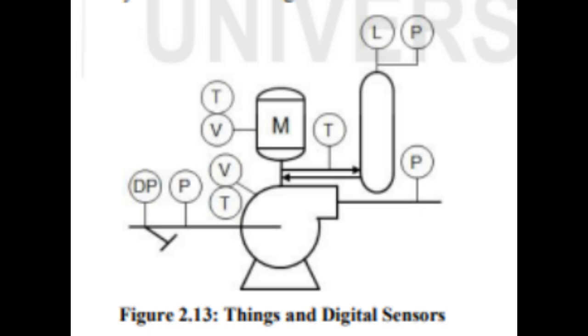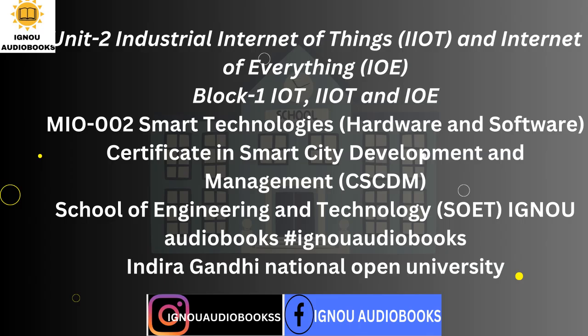Because there will be thousands of these sensors in the plant, it is critical to select high-quality industrial-grade sensors that will last trouble-free and maintenance-free for many years. The sensors touch the equipment and process, it's where cyber meets physical, cyber-physical systems. High-quality industrial-grade sensors will not cost $10 each because they are built to withstand corrosive and abrasive fluids, extremely high pressures and vacuum, high to cryogenic temperatures, vibration, EMI, RFI, water and dust ingress, and are suitable for hazardous areas etc. Good sensors are critical to run and maintain the IIoT system itself.